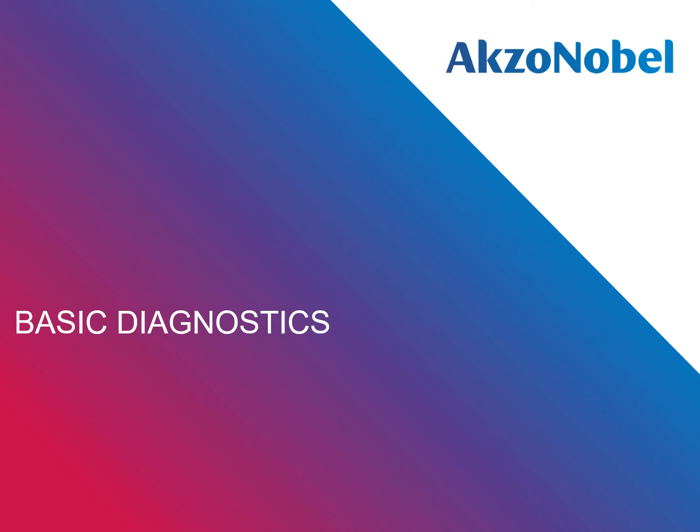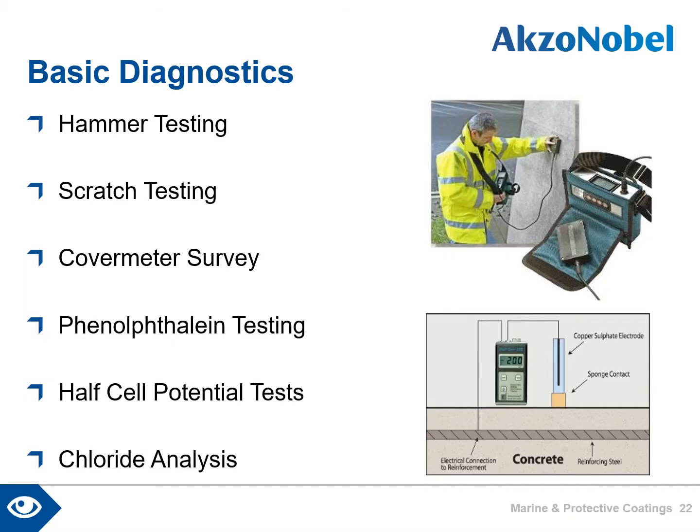We will now run through some basic diagnostics. Some of the diagnostics are very simple. By using a hammer test, the engineer will determine if there are any hollow areas in the concrete which require obvious reinstatement. Similarly, by using a chisel, scratch testing of the surface will indicate the concrete quality.